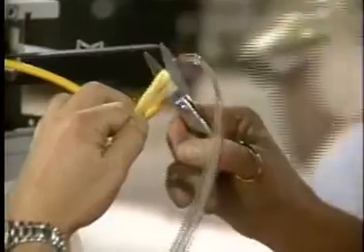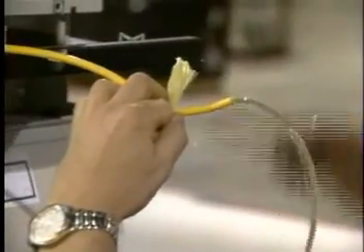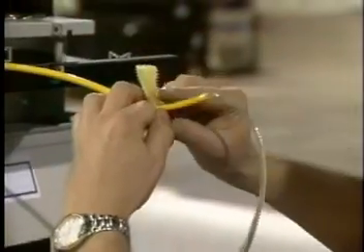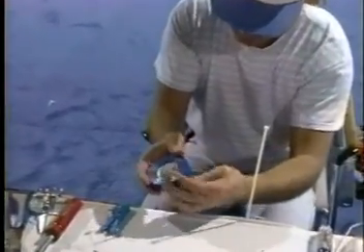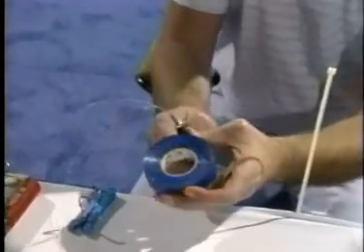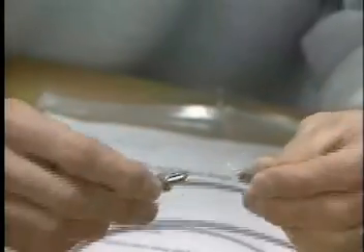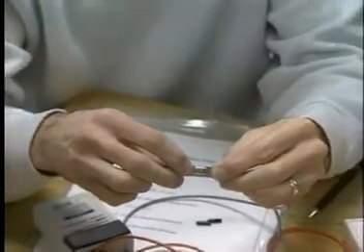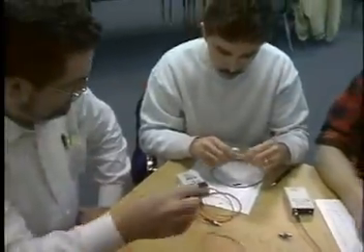In fiber, much of the loss is intrinsic, that is, due to the glass itself. However, external conditions, such as excessive bending, connectors, and splices, also contribute to signal losses. The dB, or decibel, is a measure of signal attenuation between the input and output. Fiber attenuation is expressed as dB per kilometer.